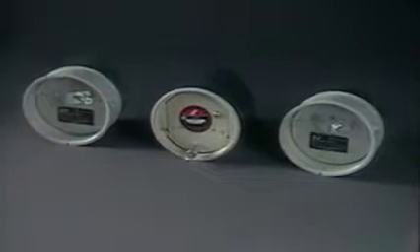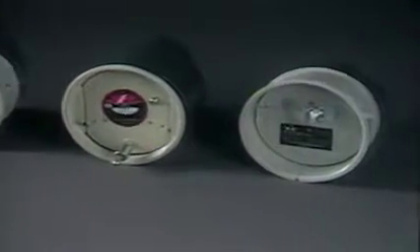Next, you'll need to have some way to regulate the draft so that it stays near its ideal low overfire draft condition. Here are some of the draft regulators available for maintaining the -0.01 to -0.02 inches of overfire draft. They all use a swinging weighted door for regulating the draft by allowing air from the room to enter the flue in the chimney, rather than pulling too much from the combustion area.